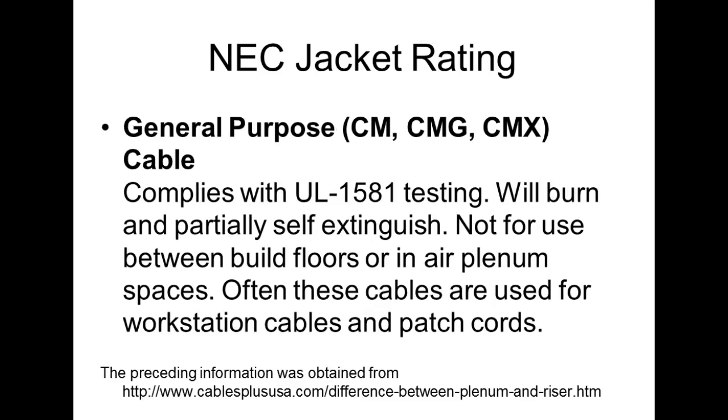CM, these jacket ratings, CM, CMX, CMG, these are what? Yeah, so these are self-extinguishing. These are for use between building floors, air cleaning spaces. Often these cables are used for workstation cables.